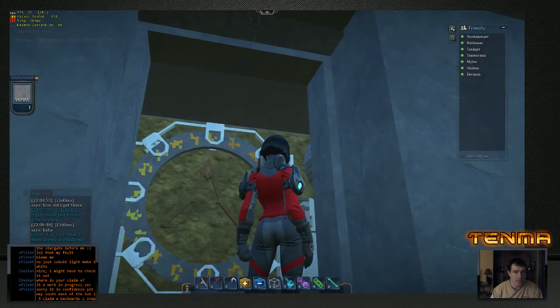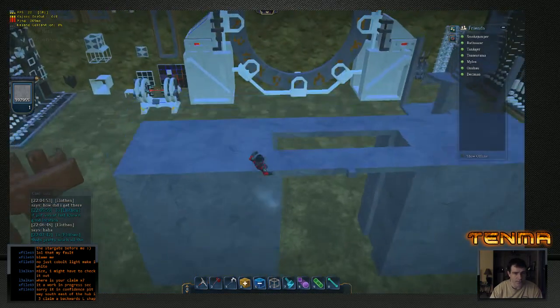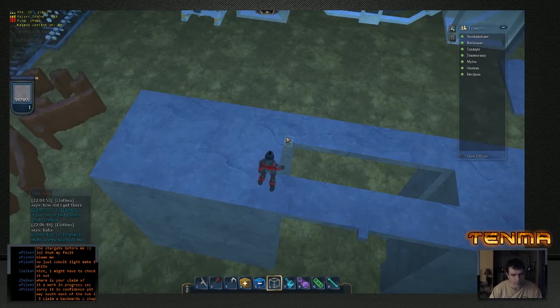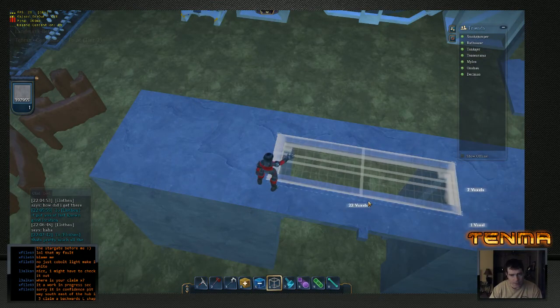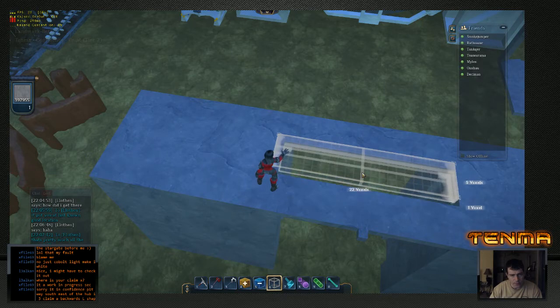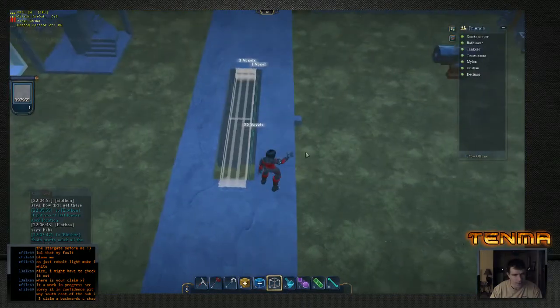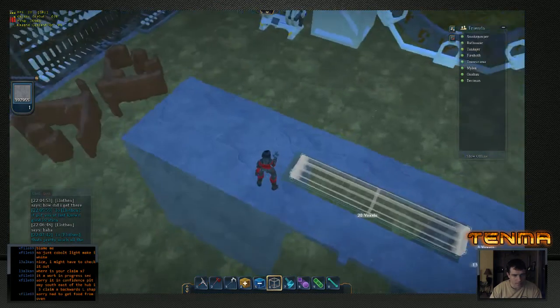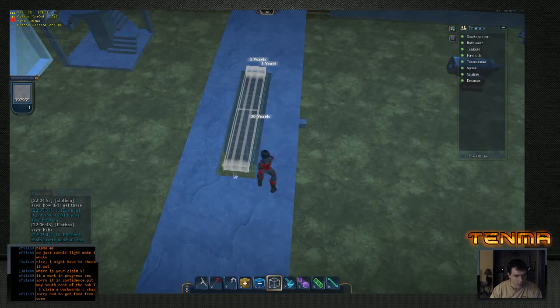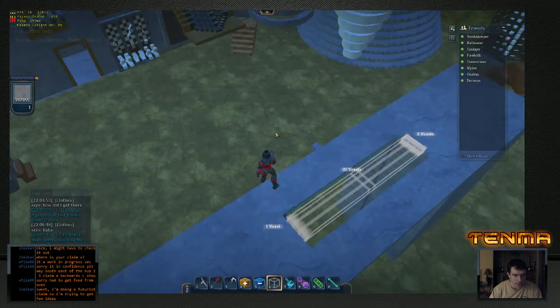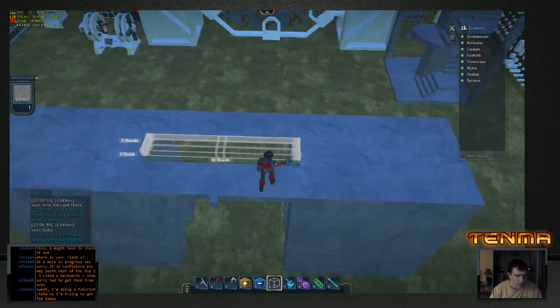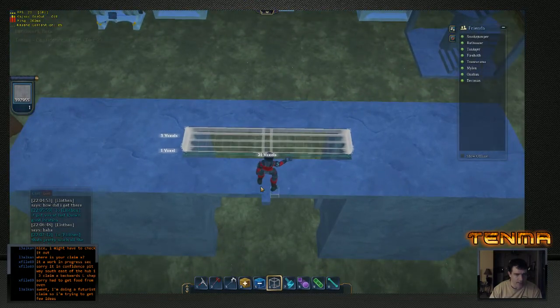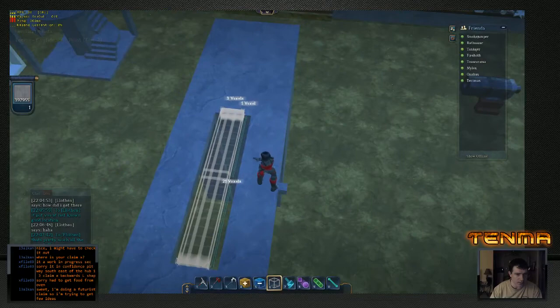All right, so the next thing I want to do, if I come up here and select this section right here, I push it in 2 voxels on all sides like this, and I push this side in 1 voxel. Quit fighting with me. I want this one to come in 1 voxel. And then this one right here, do I got that on? Yes, it's perfect. Right there. That is exactly the dimensions of my gate that I'm going to be putting in here.